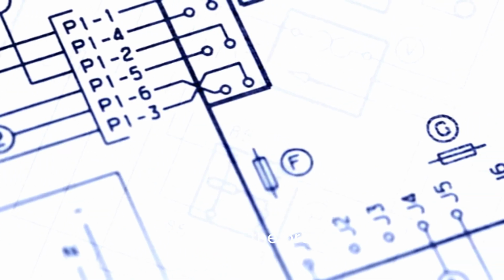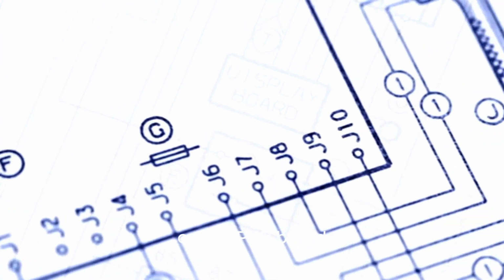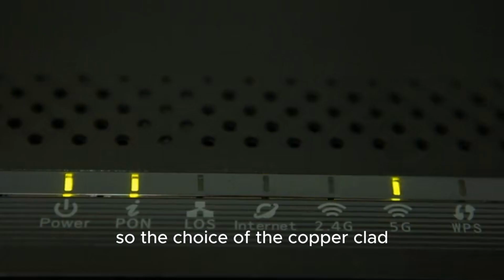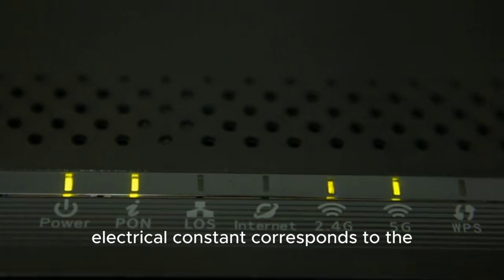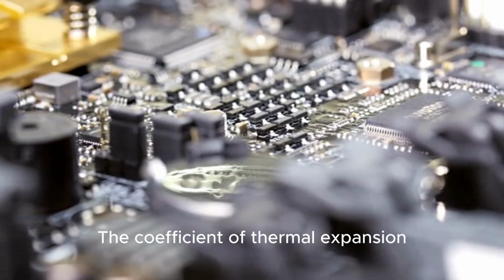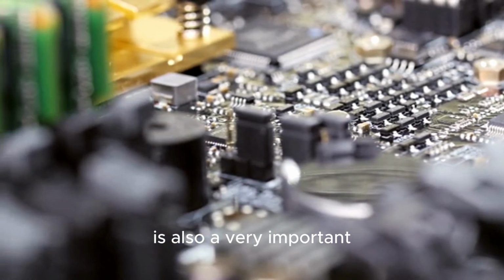The higher the dielectric constant, the more dense the lines on the PCB. When the transmission signal frequency is high, crosstalk is easy to occur between the lines, affecting the quality of signal transmission. So when choosing the copper-clad plate, the lower the dielectric constant, the better the effect for transmitting higher-frequency signals. The coefficient of thermal expansion is also a very important indicator.